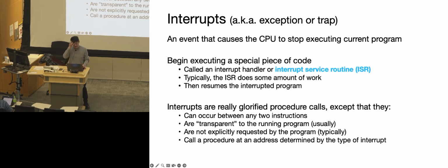Another reason is that it's kind of hard to interrupt an interrupt. We will talk more about that in a later lecture. We have priorities set for different types of interrupts, but generally it's not good to have multiple interrupts interrupting each other, and chances are you're going to run into some system exception or some errors in the memory, etc.